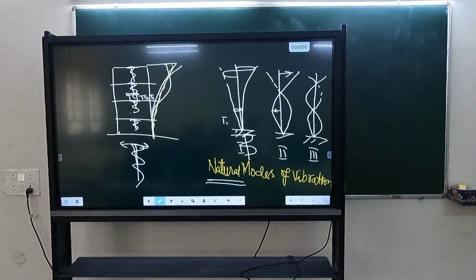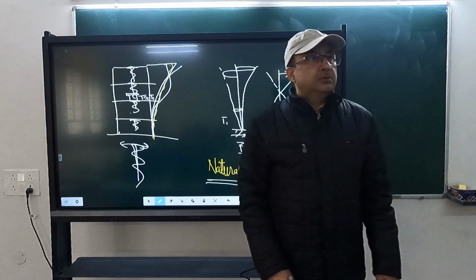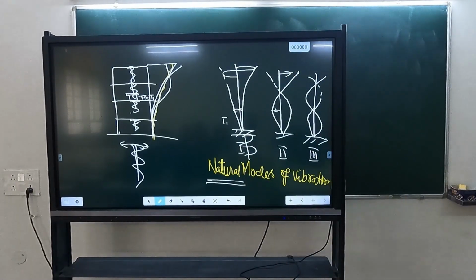It will be a resonance-like situation, quasi-resonance. Because the ground motion which came in at the ground had a frequency band, a lot of frequencies. What will the building do? Out of those frequencies, it will filter out.